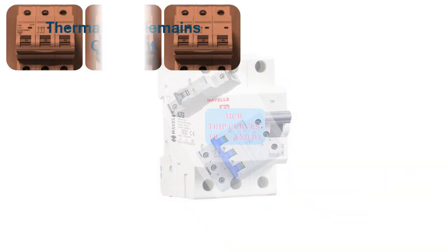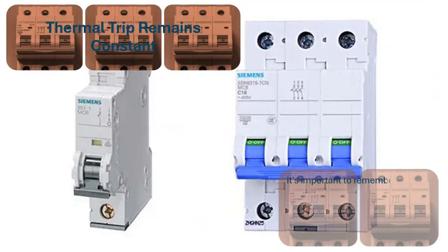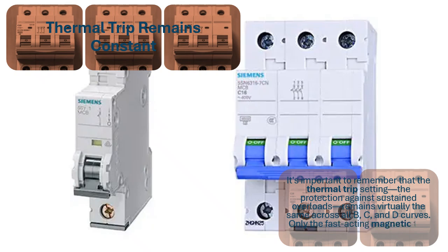Thermal trip remains constant. It's important to remember that the thermal trip setting, the protection against sustained overloads, remains virtually the same across all B, C, and D curves. Only the fast-acting magnetic trip point changes.